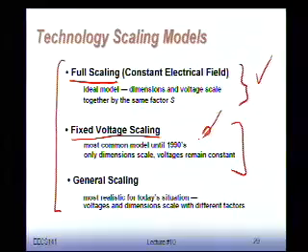You would expect now that for 65 nanometers we're going to go to 0.65 volt. Ain't going to happen. So we're actually now going back from full scaling. For a while we were at fixed voltage scaling, then we moved to full scaling for a while, and now we're moving back to fixed voltage scaling because we get stuck. We get stuck because we cannot scale thresholds anymore.